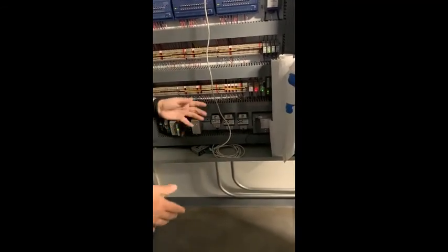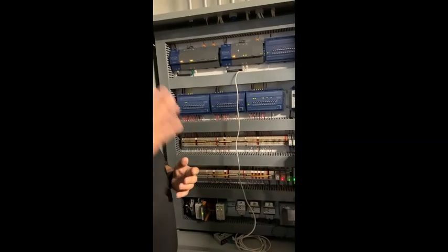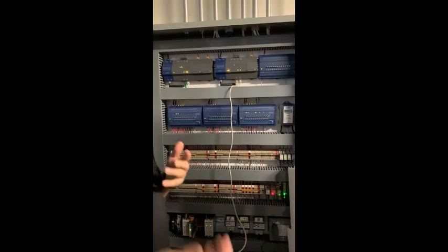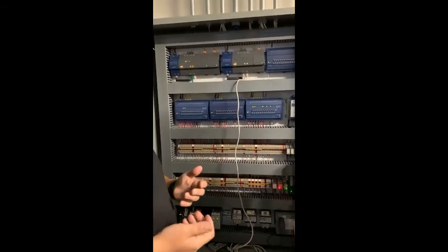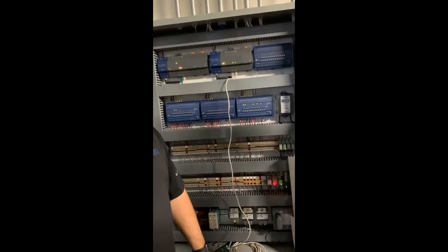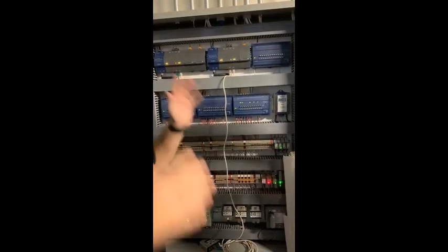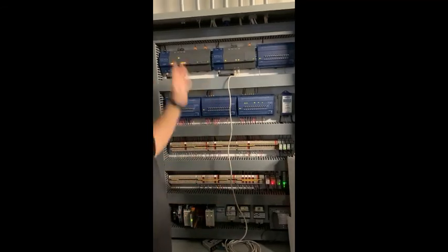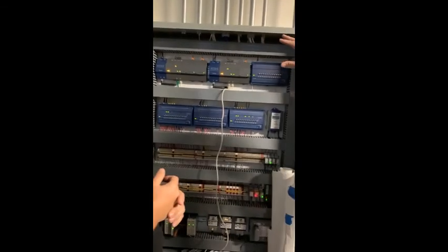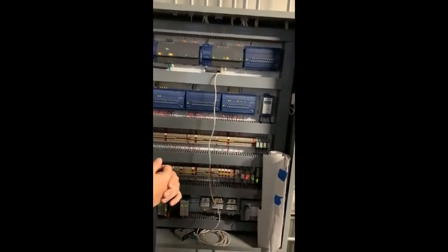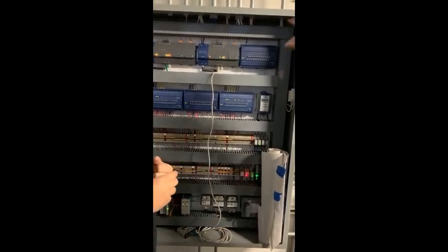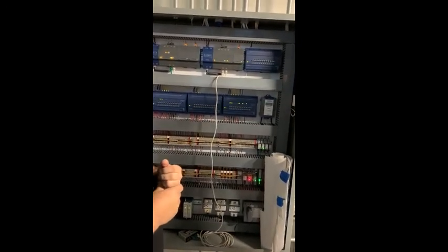Okay. So the Jaces do communicate between each other for the hot water and the chilled water, for the increase and decrease in pressure demand. And that's all done locally. So even if the campus IT network goes down, the building itself will still continue to operate how it should, because it just relies on its local connections. Everything's programmed into these. It's not talking to the computer all the time. The program settings are all inside of here.